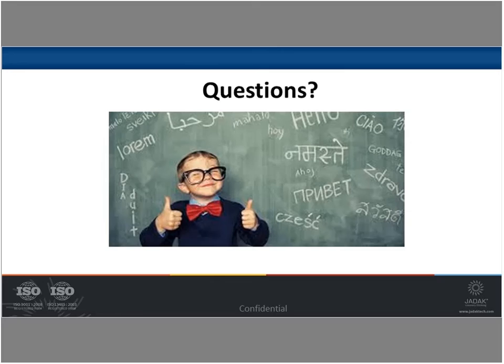Okay. How do you get a script from a PC to the camera? Oh, good question. Well, we just did a quick demo of how I developed the script on the PC. There was one thing I didn't show in Clarity. There is a device button, so you can take your actual target camera, connect it to the PC, and then you select that device, and then there's a selection to just flash the script into the camera. And then after that, you can test in an online mode where you're testing directly in the camera.